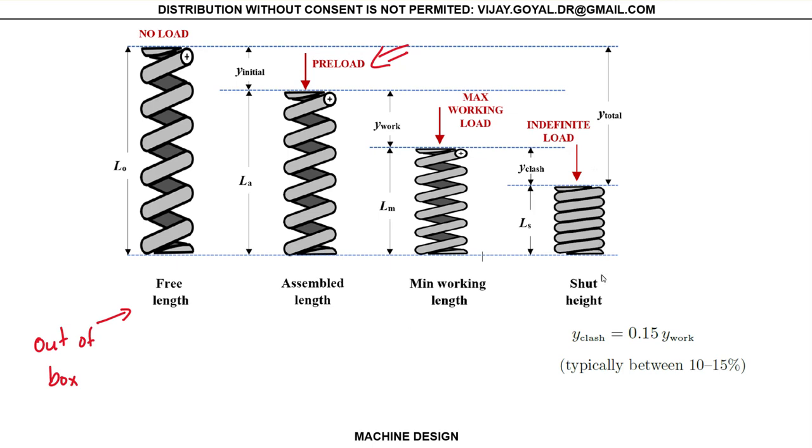And this is a very important design consideration because you don't want your coil to break when it actually slams up together. So a typical value, we can take 0.15 for your design. However, it's very common that you have 0.12, and 12% as well. But for design purposes, 0.15 is good. Okay, and then obviously it's bound by 0.10 and as high as 0.15, but never go outside these values.